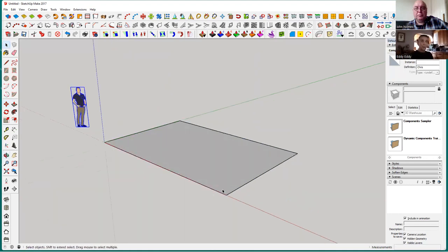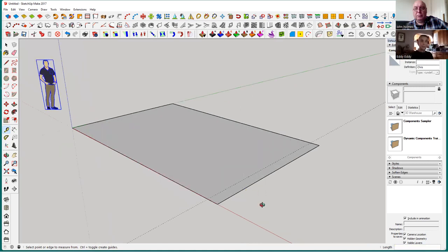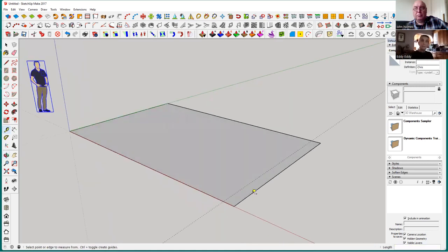First thing, end walls. Go to the tool selection, pick your ruler, click on the edge, move it up and type in 2.5. Wrong, 0.25. When we actually go to print this, this would be 0.25 millimeters. You'll see in a minute why.